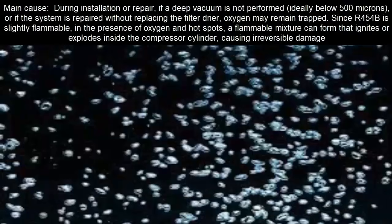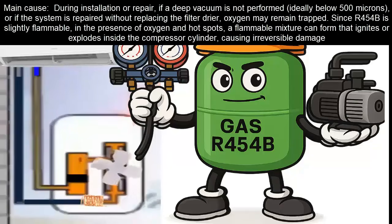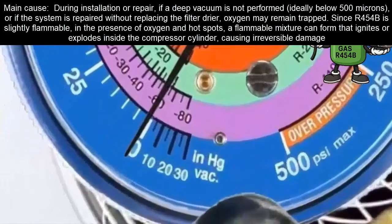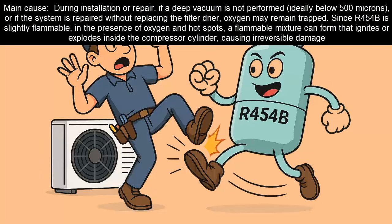Main cause: during installation or repair, if a deep vacuum is not performed, ideally below 500 microns, or if the system is repaired without replacing the filter dryer, oxygen may remain trapped. Since R454B is slightly flammable, in the presence of oxygen in hot spots, a flammable mixture can form that ignites or explodes inside the compressor cylinder, causing irreversible damage.